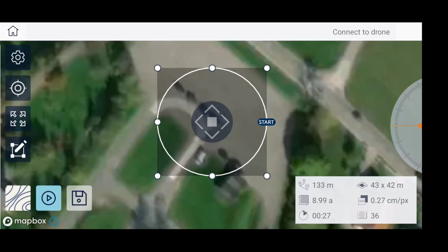Why I start with the highest circle is just because of safety. At 20 meters, there are probably no trees, no traffic lights or similar objects. You get a good idea where the drone will fly, even later on the second and third circle, which will be lower and the radius will be bigger. Then if there are some trees or anything like that, you can stop the drone and do a manual flight in addition to get additional data and so on.